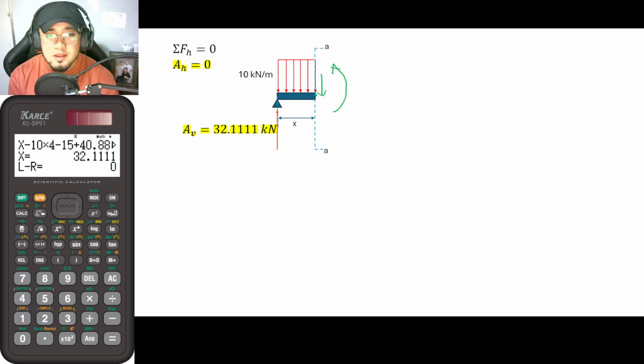Okay? And guys, just as a shortcut, instead of solving for these internal forces, I would rather lecture it this way. Just get the summation of forces vertical for the shear, and whatever the answer is here is now the internal force that is being acted upon here. Okay, so let me just write them manually. Suppose, guys, that this here is a distance x from this point.